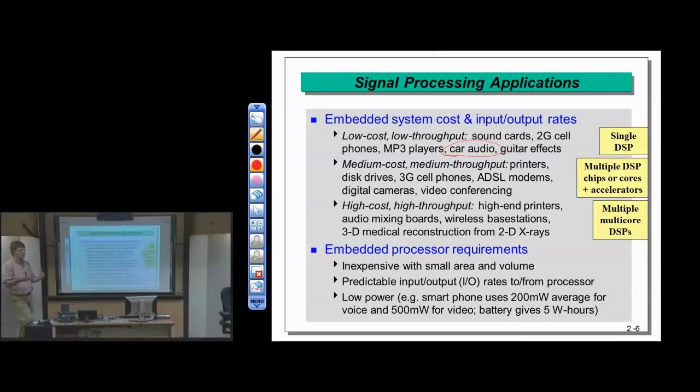You can read 32 bits, but really the 24 bits are accurate. Anything beyond that is not so accurate. It's mostly noise. So it's 24-bit audio, and if you think about the 32-bit floating point data type, it's got 24 bits of mantissa plus sign. This is a perfect match for the 24 bits coming off an analog to digital converter.